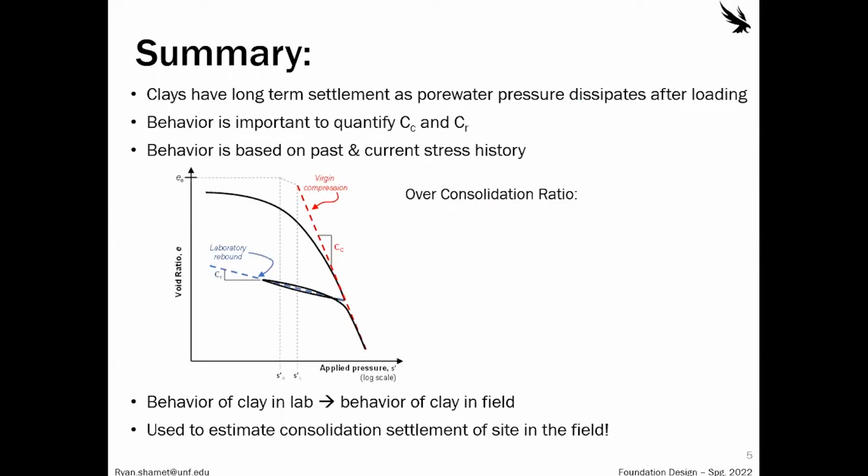All right, so just in summary from what we were saying last week, the clays have the long-term settlement, and this occurs as the pore water pressure dissipates after loading. So we only see this in low permeable material. So consolidation in sands, consolidation in gravels, that doesn't exist. There's no long-term settlement. All the settlement occurs right when you load it. So only in clay and some silts do we have this issue.